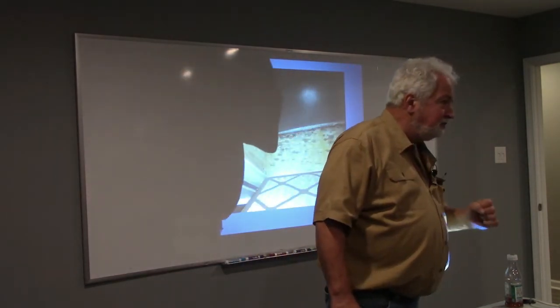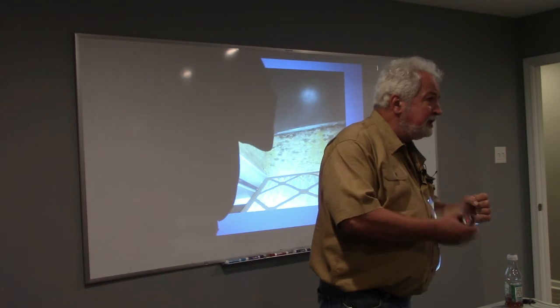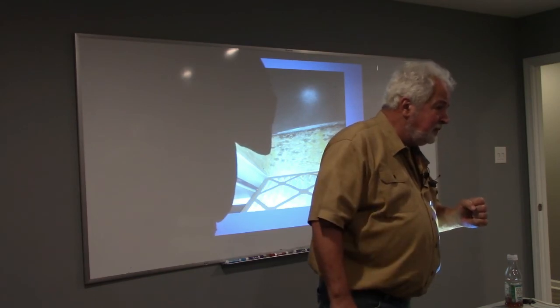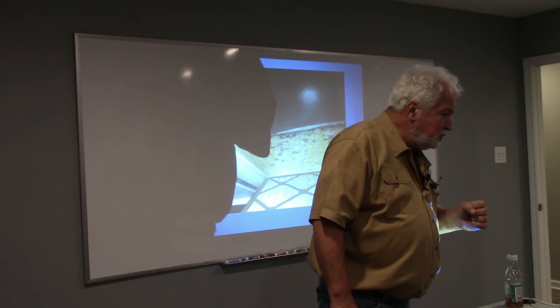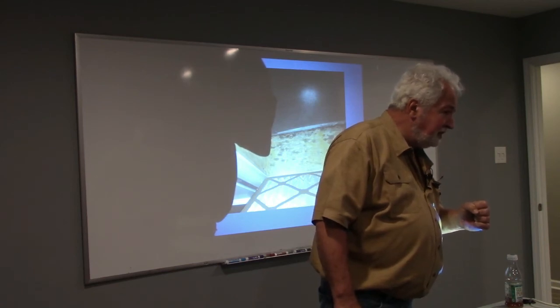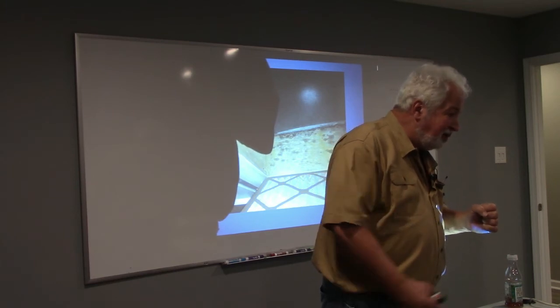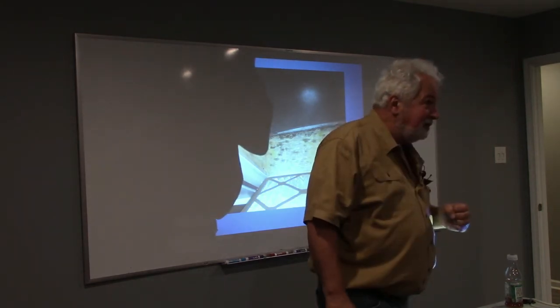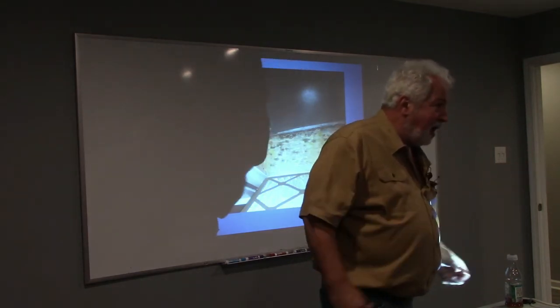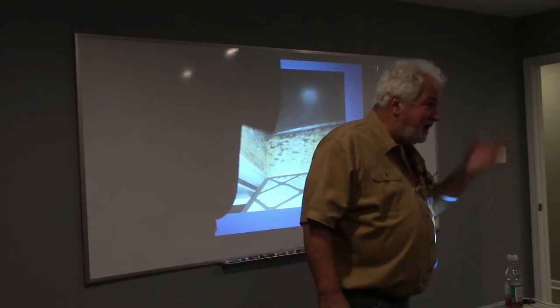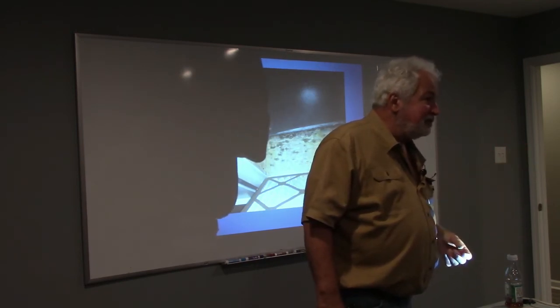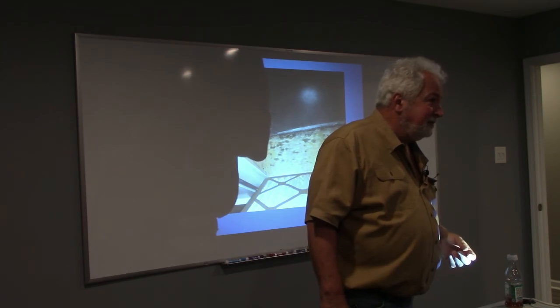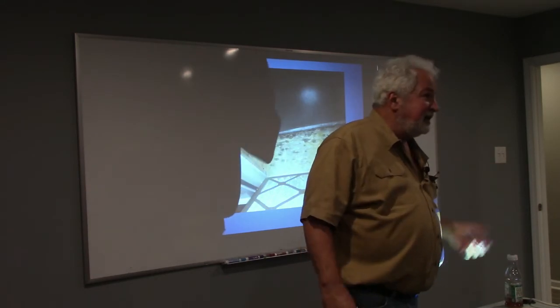If you had a straw and you were trying to get something out of that glass, could you do it with a small duct, or could you do it with a big duct? Probably small. Good. So if the duct is small, stuff's going to come up, just like you're talking about. That filter's going to go up if that ductwork is small. But if the ductwork is larger, I can get the air, but I'm not going to have the velocity. Is that right? You're telling me what's going on with that guy's return air grill? That the return is too small. Absolutely it is. And it's going to hum.